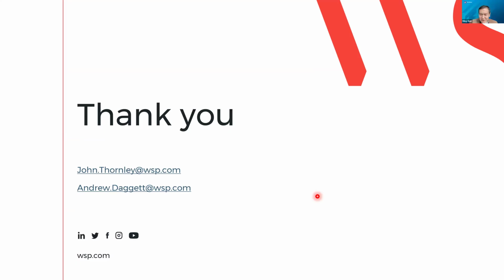Yeah. Thank you. For an adfreeze pile, how long do you have to wait to load such a pile? First, it depends on when the pile was installed. Like we've talked about before, wintertime construction is ideal for installing your adfreeze piles, and you can take advantage of some of those temperatures. In summer, you could be waiting a long time. And the simplest way to do that is probably to monitor it.